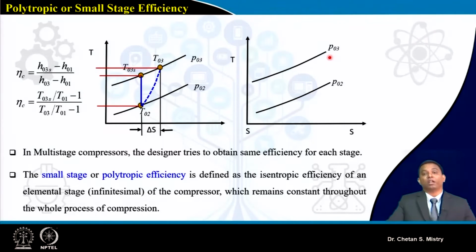As we have discussed earlier, the axial flow compressor is a very sensitive device and has aerodynamic limitations, and that's the reason why we go with a number of stages. Suppose I make my compression process using different numbers of stages. Let me put this process on the TS diagram we have learned. For my first stage, this represents my isentropic compression, and this represents my actual compression.